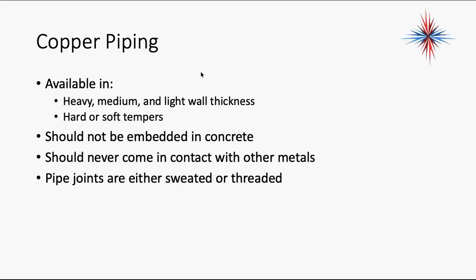Pipe joints are either sweated, which in other words means soldered, or threaded. Now, in refrigeration, we started talking a little bit about brazing. I know someone was starting to work on brazing those projects, the boards together. But when we're talking water pipe, we cannot use braze. We use solder. When we're talking refrigeration, we don't want to use solder. We want to use braze. It has to do with the pressures.